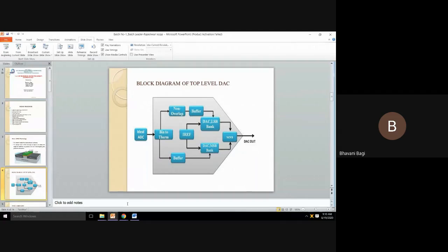It works by summing the current produced by an array of current sources. The load resistor is connected to the output of the current sources. High resolution converters of greater than 12 bits have been implemented. Also, a 12-bit design was chosen to balance resolution and achieving high bandwidth. Two sub-DACs are used to segment the bits.